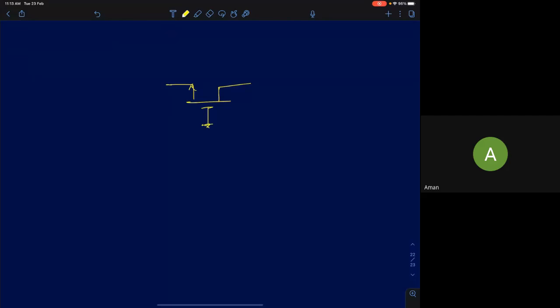So in the previous lectures, we discussed the common source and common drain amplifiers. If you see, both common source and common drain amplifiers are fundamentally power amplifiers. They draw very little to no power from the input, but they deliver a finite power to the output. Therefore, we said both these stages offer a huge power gain. And we said that's the definition that distinguishes active devices from passive devices.